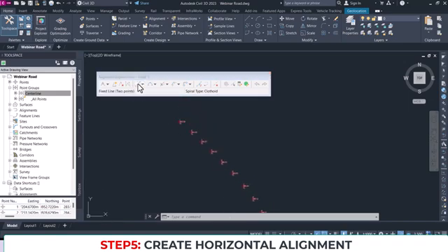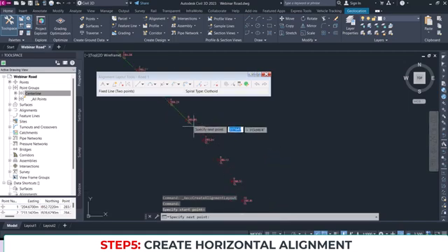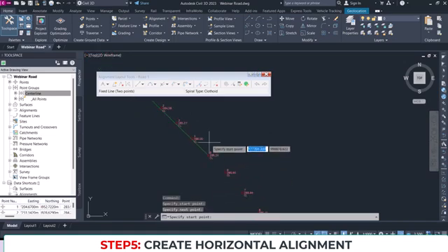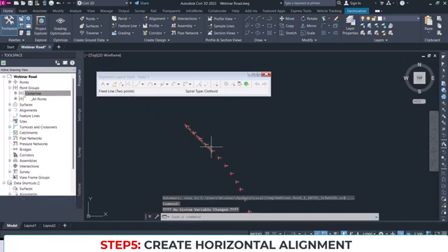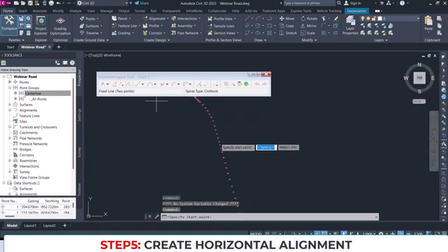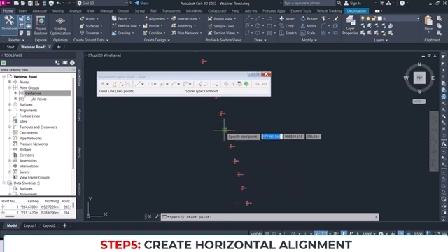Okay, I'll just pick up a line here and then start from the beginning. Once I use that, I find a straight section and end it. Up to here I believe my alignment is straight, so I press enter. We are not done of course, so we have to find another straight section.